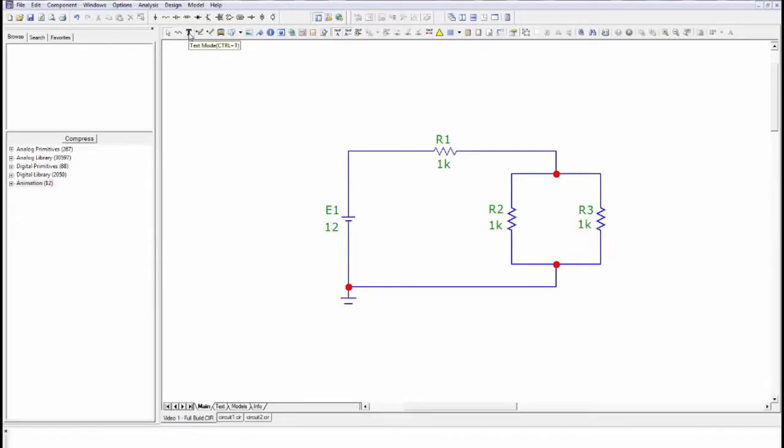Text tool here, so if you want to put headings in on your schematic or markers, or record some note or whatever on your schematic, just click on that, put it into the area that you want to. Hey presto, you can change the font and the colour and everything. The wire tool we've already seen. Diagonal mode wiring, that's useful when you have that 3-phase circuitry in place.